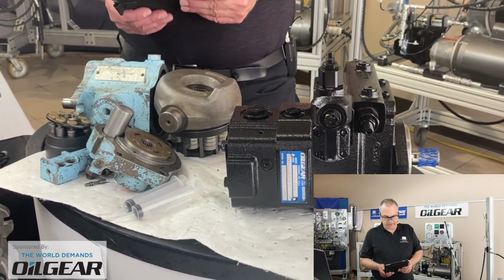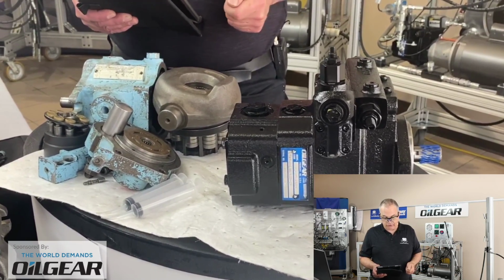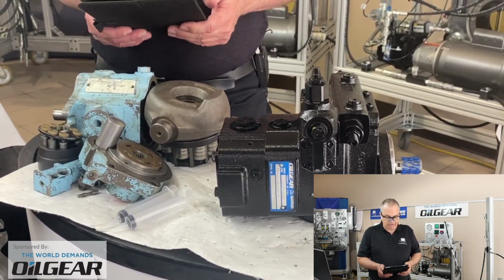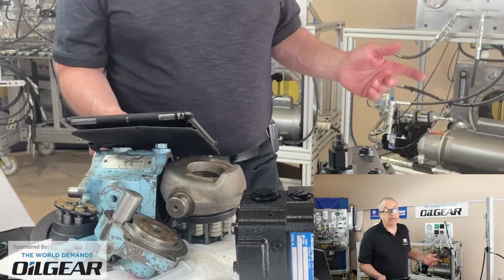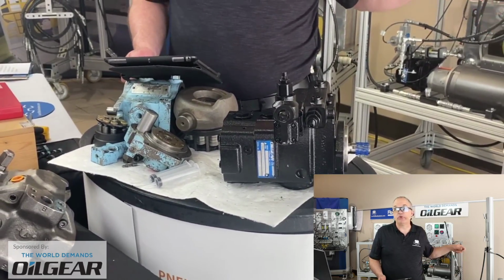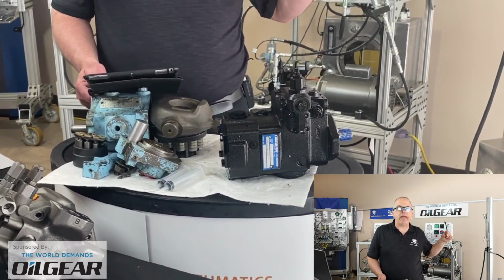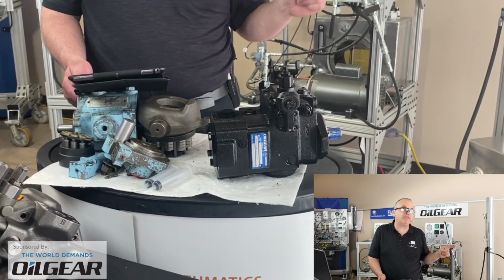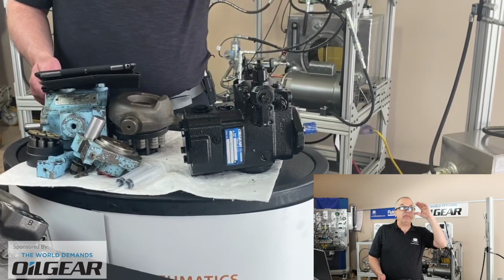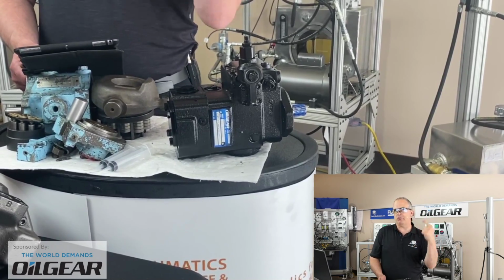Andrew also has a comment there. Yeah, okay, great. Oh, yes, very good point. I did not point out that. The electric motor current is at its lowest while the pump is at maximum flow and at zero pressure, yes. But what you would also find out, Andrew, is that when we get to the flow cutoff point closing in the needle valve, the current goes to a very high point, and then just as you close in that needle valve, all of a sudden the amperage drops off again, because you can maintain high pressure, but if you reduce the flow volume, that does not take as much power from the prime mover as it does when we're at both full volume and full pressure.